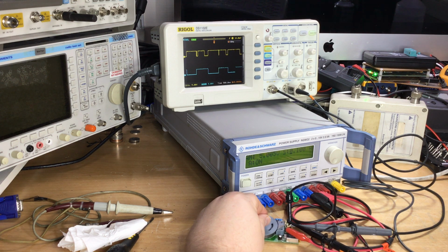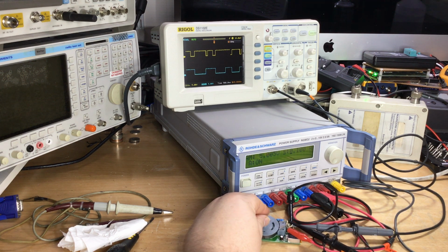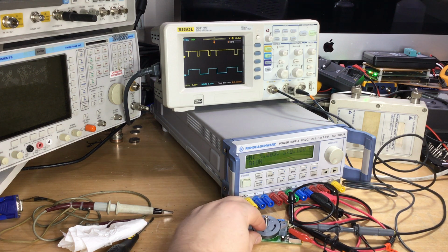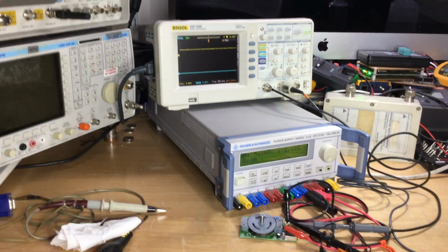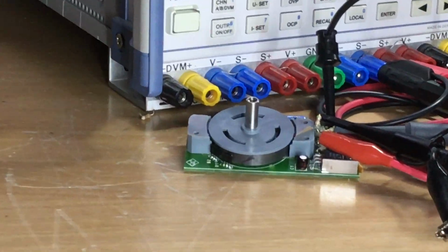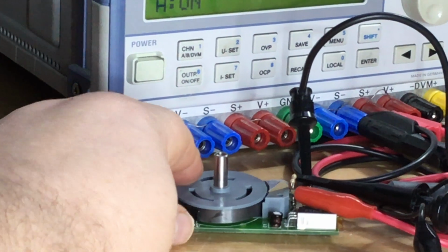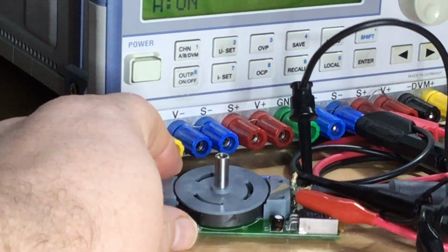But I can see already it's gone highly erratic as the top pulse is there. So one of the Hall effect sensors isn't working properly, and the other is, which is signified on the bottom of the trace there, in the different colour. So yeah, it looks to me as if we've got a problem with this bottom Hall effect device there. So if we look at that more carefully, it's this one there at the bottom, that one out of the two.